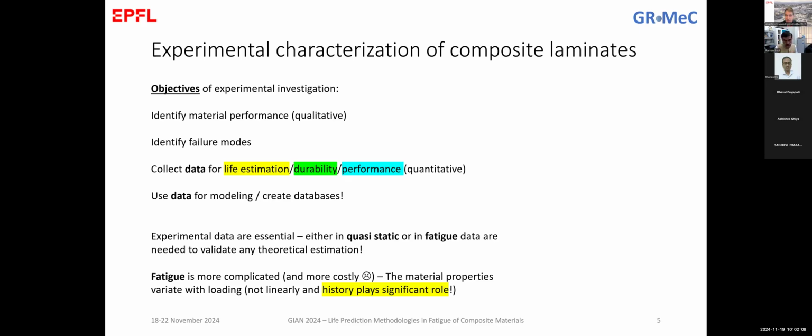So I'm together with you. It's a very significant point and needs to be considered in all the analysis. Additional reasons for interruption might be a failure in electricity. Right? We've seen it a lot of times. You put a test there, you go home, and then during the night there is a failure in electricity. You go back next day, you see the machine is stopped, you restart the test without considering this interruption, and this gives different falsified results.